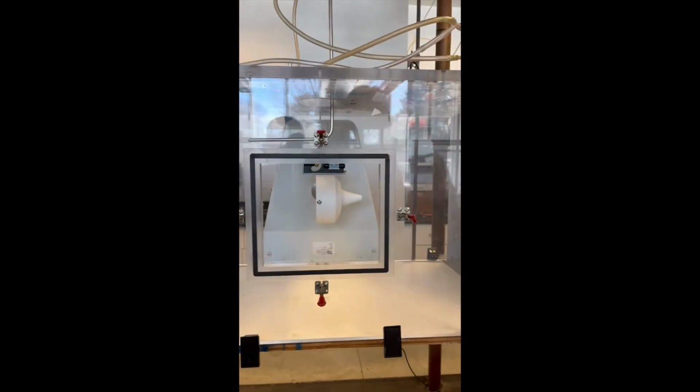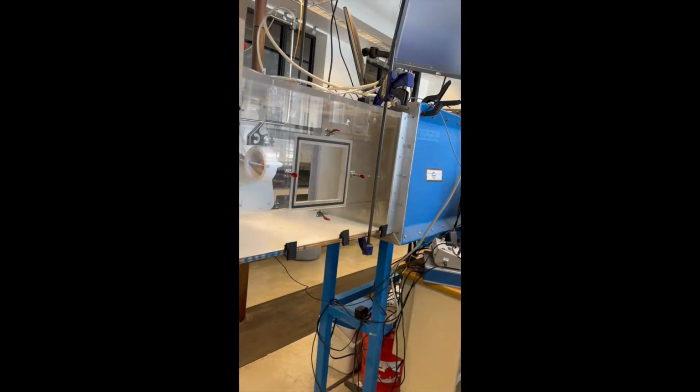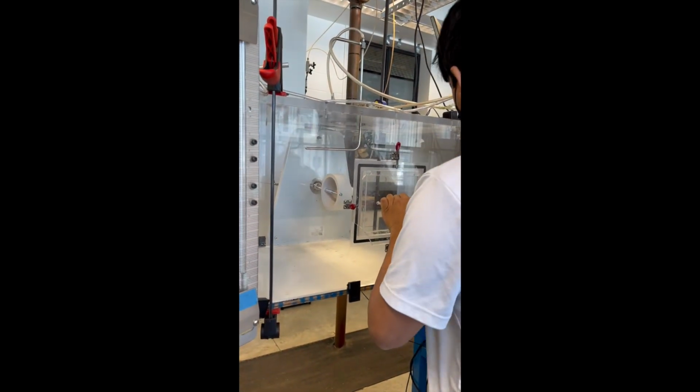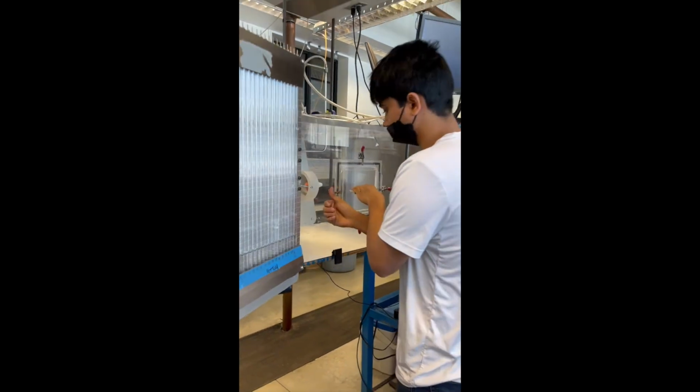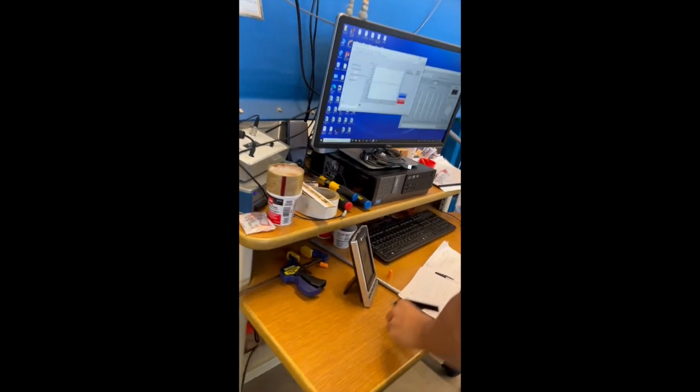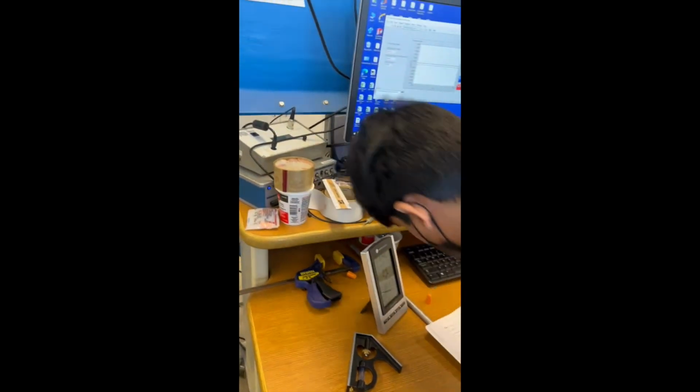Now to move on to the wind tunnel testing procedure. The first step in my procedure was to measure the screw points on the strut. From there, using those measurements, I would use the drill bits to drill holes in the nozzle so that they can be attached to the strut via the 1/4 20 screws and nuts. From there, using the nozzle attached to the strut, I would place the nozzle in the wind tunnel and tighten the set screws to ensure that the nozzle would not fall off during experimentation.